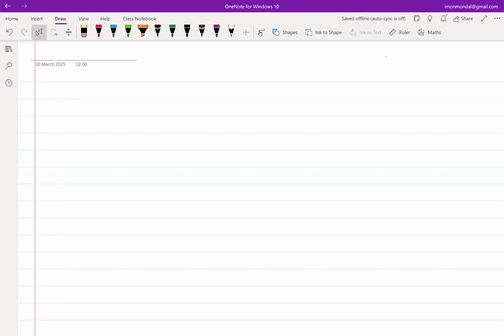The bigger problem was, when you want to characterize your device, called the device under test, or DUT, you have to connect some source. You have to connect the source and the device through a cable. The cable will have some finite length, which means the signal will take some time to flow. When I say time in this regard, I mean that the time is a significant portion of the time period of the signal.